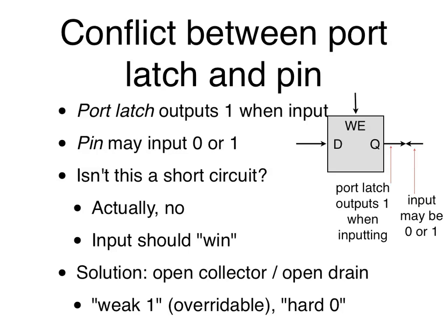This is really just to give you another look at this. When a port is outputting a 1, that allows the pin to be either 0 or 1. And because of the pull-up, that conflict between a 0 and 1 is not a short circuit, okay?